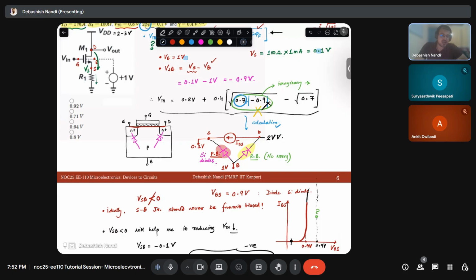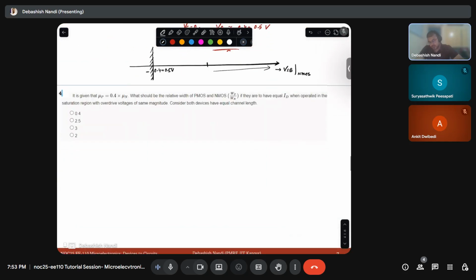Okay, you will get your answer by doing that, but physically, think: by applying a positive voltage to the body, you are increasing the source side energy, right? That means your electrons can move freely, or your threshold voltage should drop. Why will my threshold voltage increase? Right? Yes, sir. Yes. So that is one aspect of it.